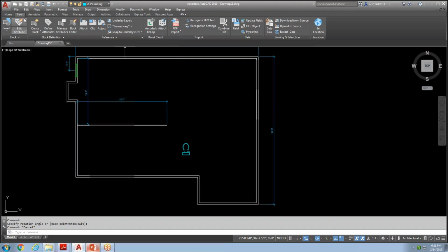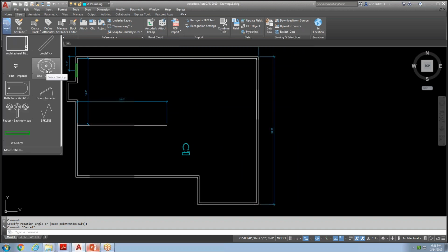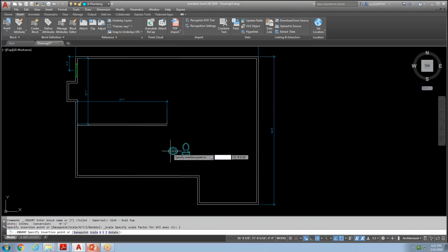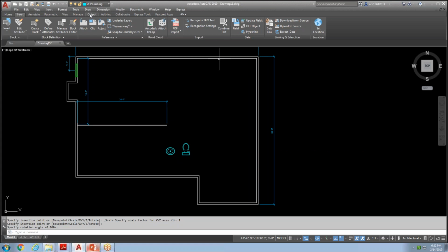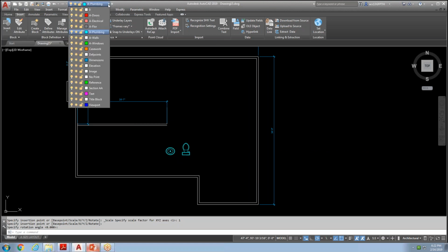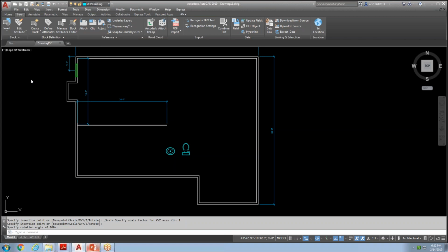And then the other content that you'd want to go ahead and put in here is actually the sink top. And I'll go ahead and just drop that there. And as far as that goes, you would go ahead and surround that just with a line on the Casework layer. And there is a layer, I believe, called Casework. Yeah, Casework right there. You'd make a layer on there called Casework.